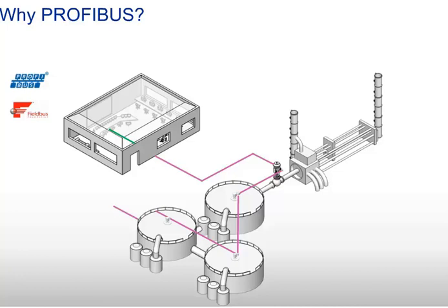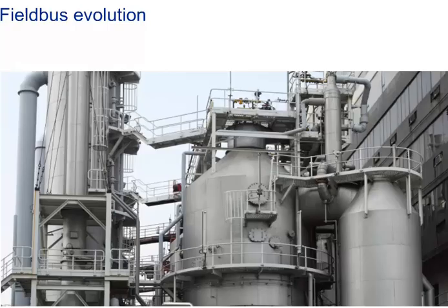For predictive maintenance, the bus technology is the only way to quickly transmit process-related data to the control room. A Fieldbus device, for example, a positioner, constantly transmits information about the positioner and valve health to the control room. Any changes are thus reported to the service personnel as early as possible. This helps to avoid unplanned plant downtimes.